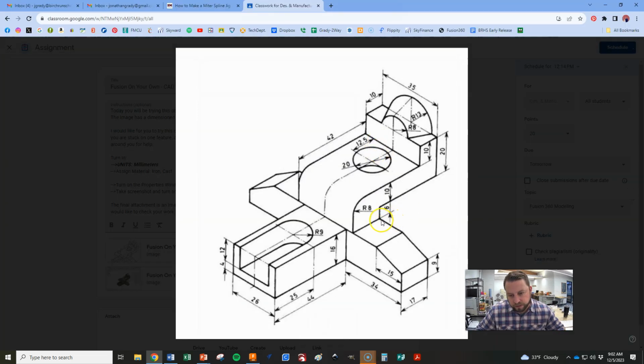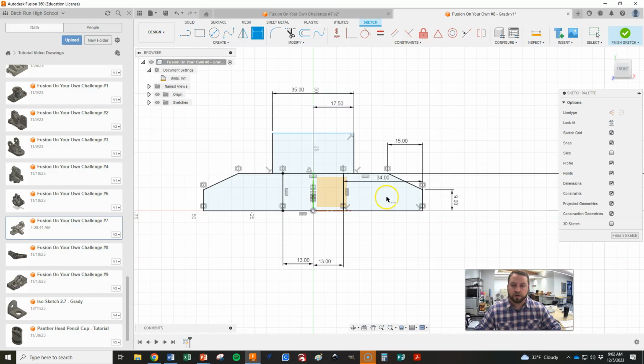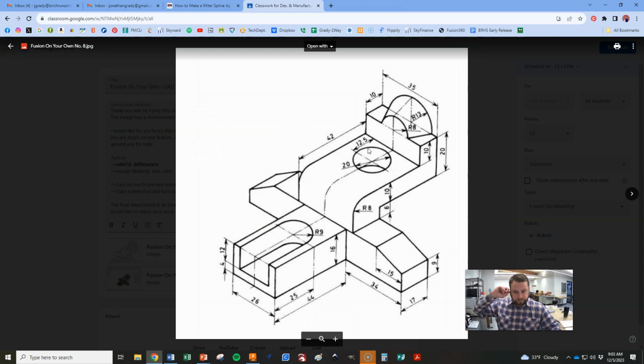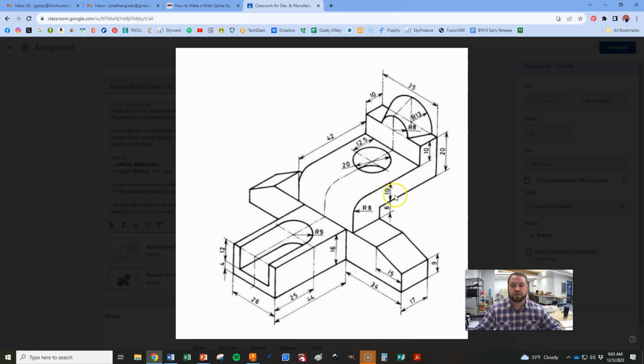And really what we need to do is we need to go up 6 and then 10 more with 2 lines. So I'm going to draw in another line in here across there, and then I'm going to dimension from that to that is going to be 6. And from that to that is going to be 10. And so now I'll be able to pull this back all the way that I need to go. So we should be all set here.